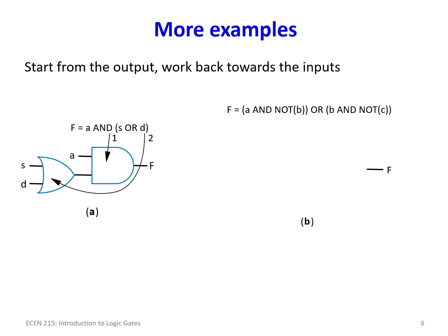So here we have another one, A and not B, or B and not C. So again, we start with the F, and we have two parentheses here. So we're going to go ahead and look at the ORing first, and then we're going to come back and do these individual parts. So you're working back through the Boolean algebra in reverse. Normally you would execute the Boolean algebra by first looking at precedence, which would be inverting the B, doing the AND, in other words, doing what's inside the parentheses first, and then finally doing the OR. But when you're creating the logic gate representation of the Boolean algebra, you kind of go backwards through the logic. You start with, in this case, the OR first.